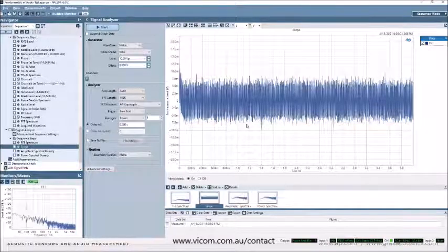Log chirps or exponential sine sweeps allow us to derive those measurement results very rapidly, usually on the order of 10 times or more faster than a traditional step sine sweep. So I would say it's a practical or a pragmatic reason to do that.